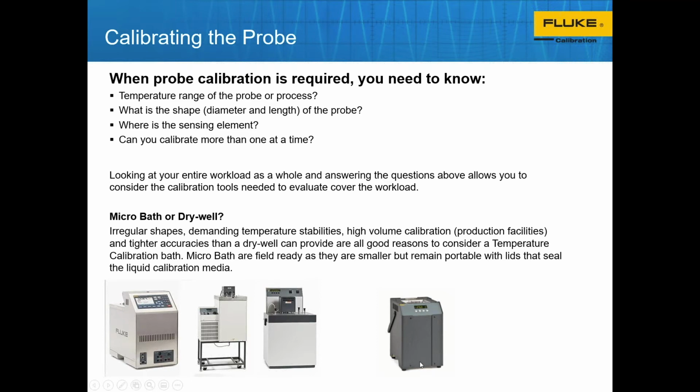But there is a portable version. It has a screw lid on the top here. You can unscrew the lid, and this allows you to do odd shape or regular sensors in the field. And they're very popular. They're quick compared to these ones. These ones take hours to stabilize. This one here takes minutes to stabilize. So just be aware that they're out there so you're not force fitting probes into applications that were not intended for a dry block.